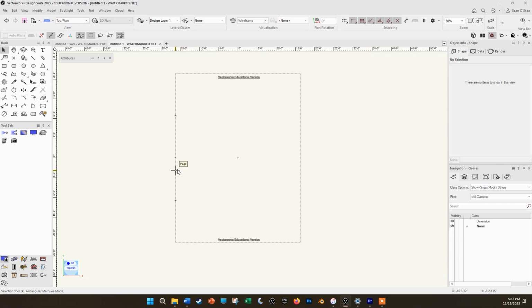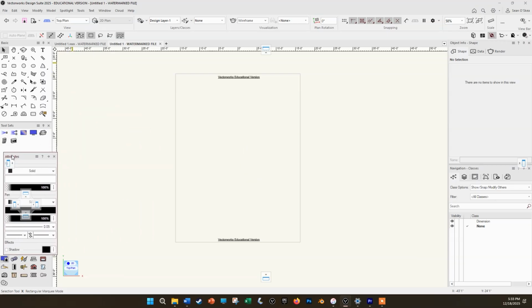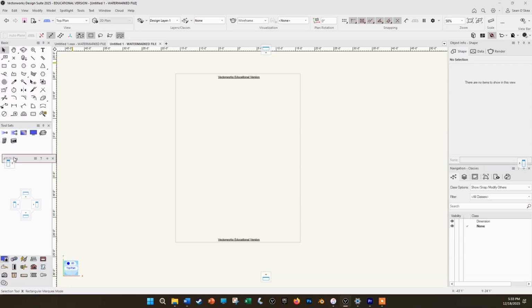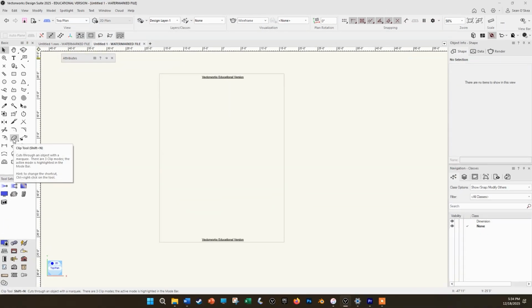If you want to dock a palette, click and drag its title bar in the direction of where you would like to dock it. And you get these little blue guides that appear letting you decide where to place the docked palette. We can also very easily change the shape of the palette simply by placing our cursor on the edge of the palettes. And notice that the arrow turns into two small arrows pointing away from each other. If you click and drag when you see this icon, you can shrink or expand the palettes. Here I'm pushing the basic tool sets in a little tighter, and then I'm finding the horizontal break between the two palettes and pushing the border down a bit so that I can see all the basic tool icons, but I don't have a lot of wasted space.